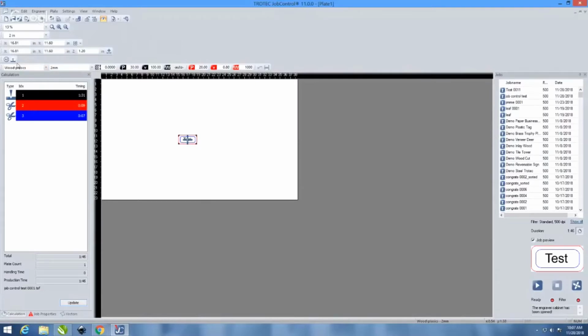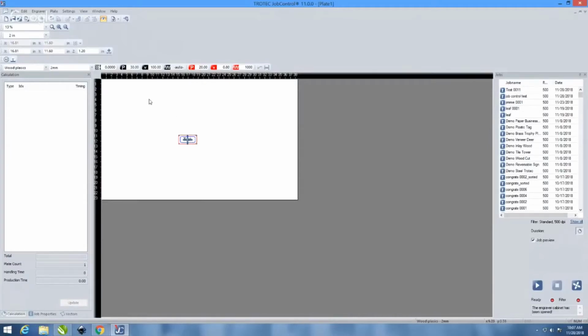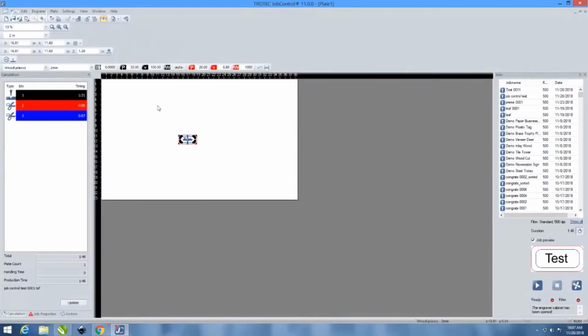Also, Anthony, could you show the markers? I think that it's a very important, great tool. So you might want some markers. What markers will let you do is position. There may be many applications why you might use markers, but essentially, I use F8. You can move your laser head to a position.